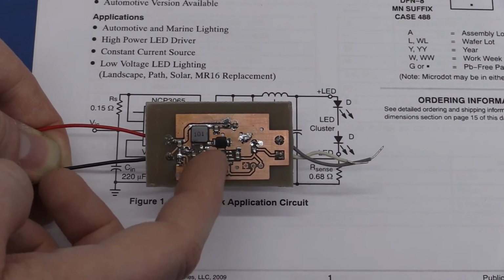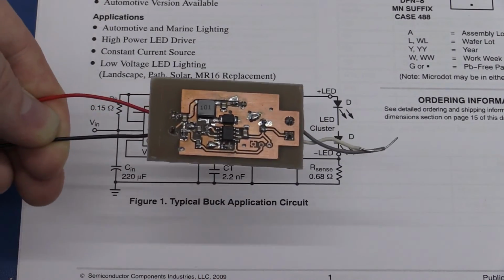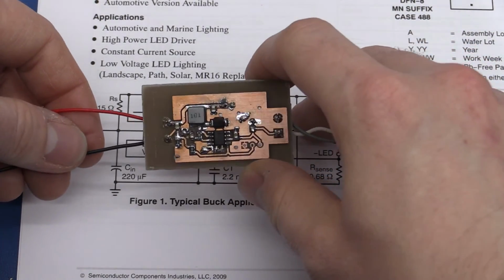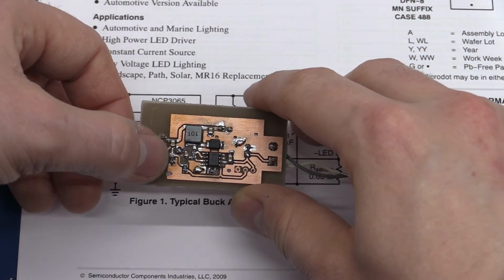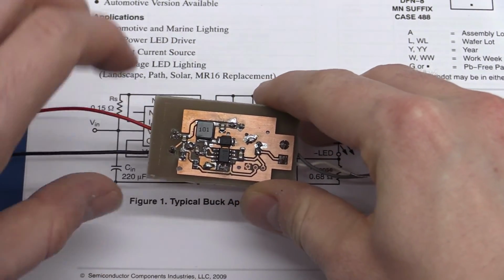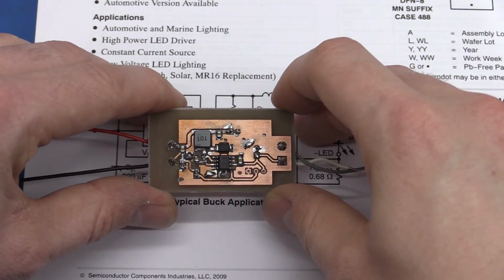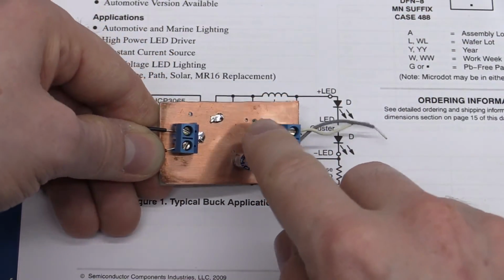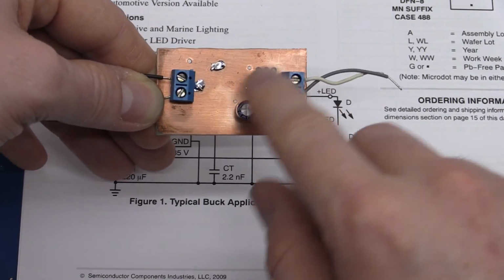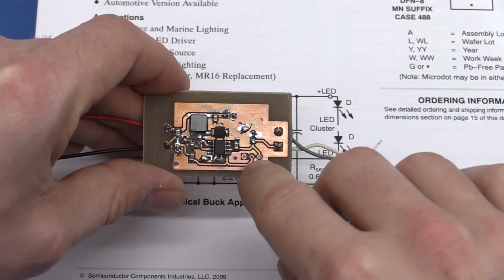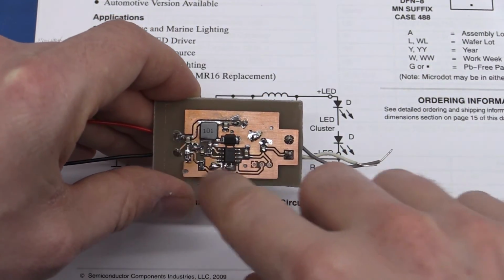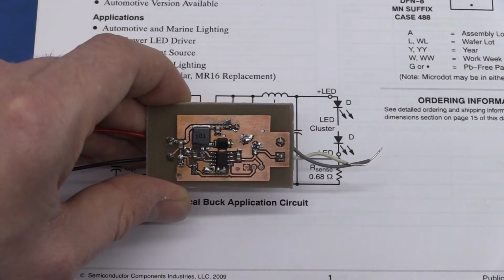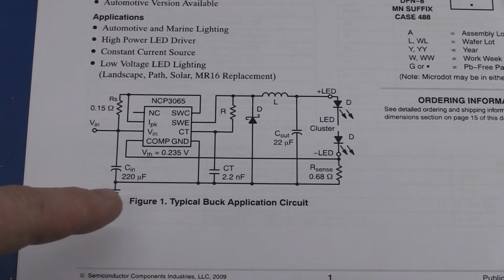Apart from the regulator, I just used parts that I had laying around. Perhaps the inductor is also larger than it should be. And I could use smaller resistors, but here I just have 0805 resistor kits, so that's what I used. And some old, probably not very good electrolytic capacitors, and then in parallel with some ceramics, just to knock down the impedance a little bit. You can see the circuit is really simple.